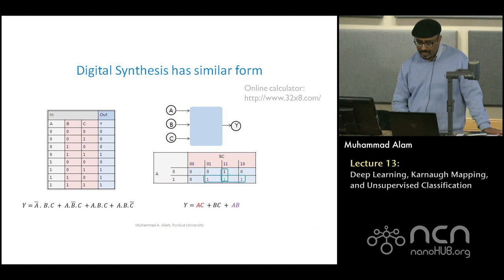You generally can do it in either of 2 ways. You can do it as a sum of products, which is you just check everywhere the output is 1, and then you write the corresponding expression. For example, this is 1, so therefore it will be A bar, because it's 0, so it's A bar, B and C, that's your first term. And then there are 3 other terms that are 1. You can easily convince yourself that this would be your network. Y has that particular expression.